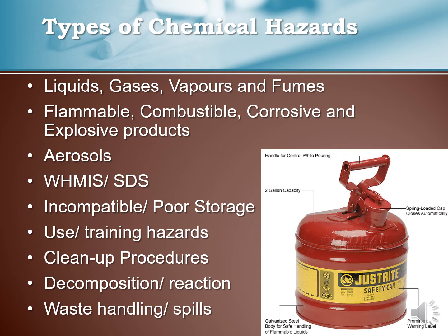Gas cylinders not restrained or stored improperly would also be of concern. This may happen in science or welding areas, or there may be no cart available to properly transport the cylinder.